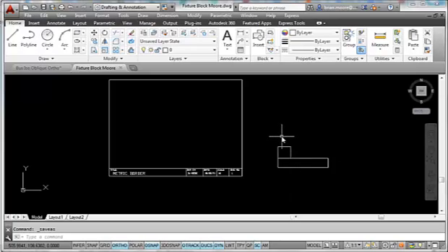We're going to place the views 40 millimeters times the scale factor away from the other views. So to do that, this is a 1:1 scale drawing, so I'm just going to offset by 40. So I went with the offset command. I typed in O for offset, and then it asked me to select the object, the distance, and I typed in 40, and now it's asked me for the object and the side to offset. While I'm in here, I'm also going to want to do a right-hand view, so I'm going to do the same thing over on this side. That just tells me where to start this top view.